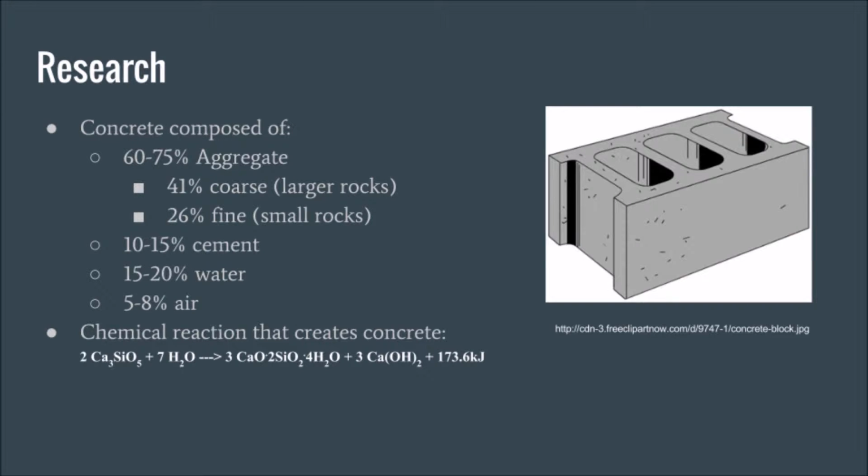Step 4 of the engineering design cycle was to search for solutions. We researched what makes canoes strong and applied what we learned to a buoyancy equation to prove on paper that a concrete canoe could float. Next, we studied the actual makeup of concrete to try and assess how we could change the material to improve our design. We landed on the idea that replacing the coarse aggregate in the concrete would lighten the canoe without compromising much of its strength. This took hours and hours of brainstorming.